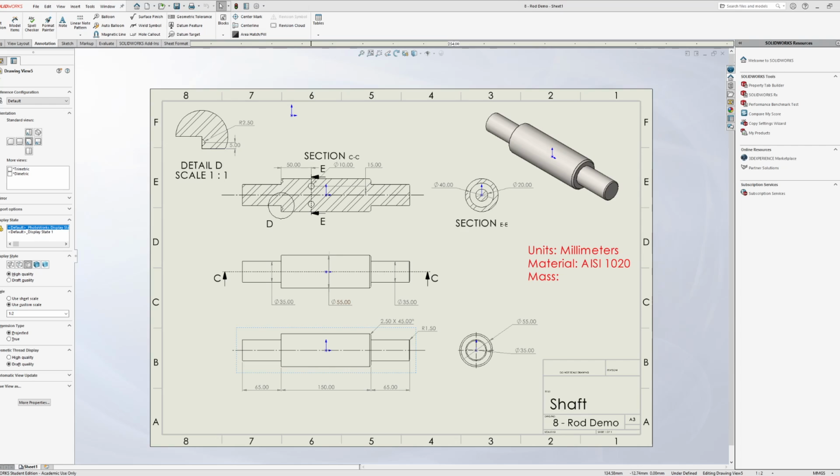Usually, you're not going to need to play with any of the scale ratios that are greater than one, like 2 to 1 or 5 to 1 or any of that stuff, because then you're talking about massive diagrams, which there should be really no reason for in many of the things that we're doing here. So I'd probably just say make sure that the annotations are reasonably readable. Make sure that the overall scale of the diagram is reasonable. And I know reasonable is very subjective, but I would say use your best judgment.